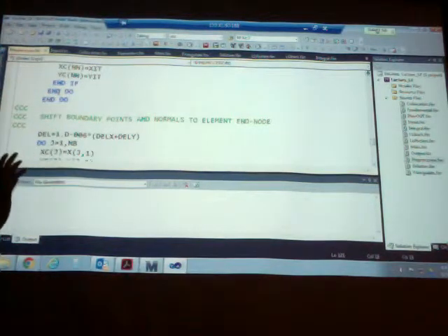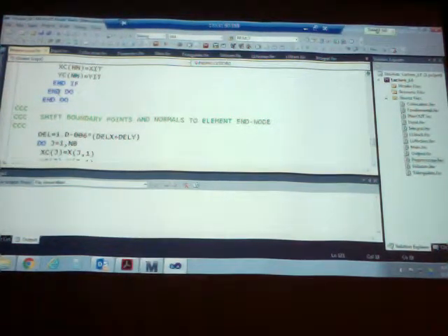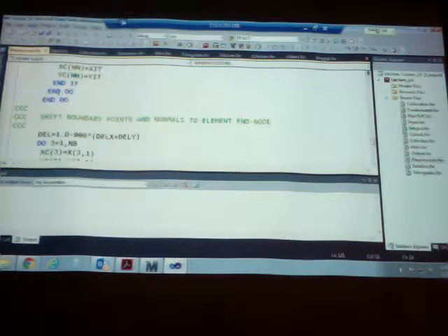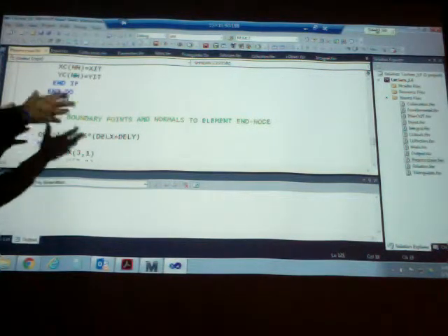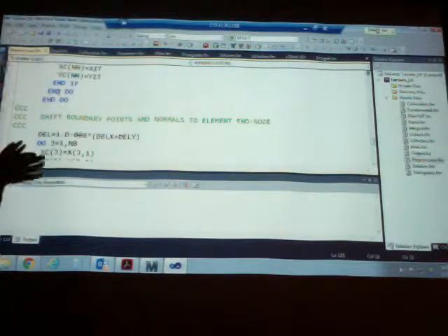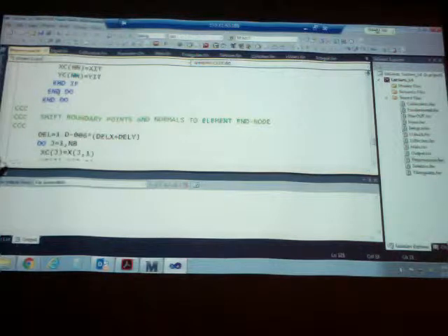Because remember, the BM, the way we set it up using subparametric elements, is going to calculate the temperature and the heat flux at the center of each element. We cannot send that information through a triangulation routine. The triangulation routine is going to need the vertex values. So what we're going to do is position also boundary nodes at the end of each element. So part of the internal information is also boundary information. But it's boundary information that is not necessarily at the center of each element, but at the vertex of each element. Is that clear? So it's going to generate internal data plus additional boundary data just for post-processing.